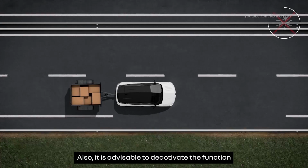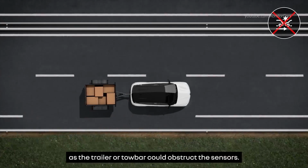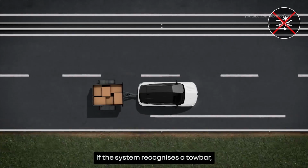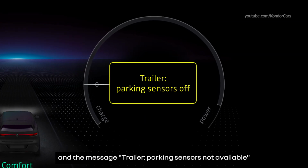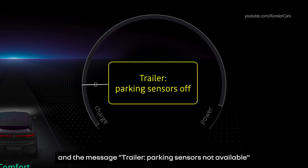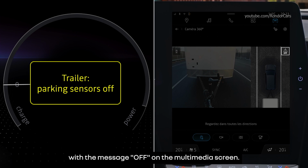Also, it is advisable to deactivate the function if you're towing a trailer, as the trailer or tow bar could obstruct the sensors. If the system recognizes a tow bar, the feature is automatically switched off and the message, Trailer, Parking Sensors Not Available, is displayed on the instrument panel with the message Off on the multimedia screen.